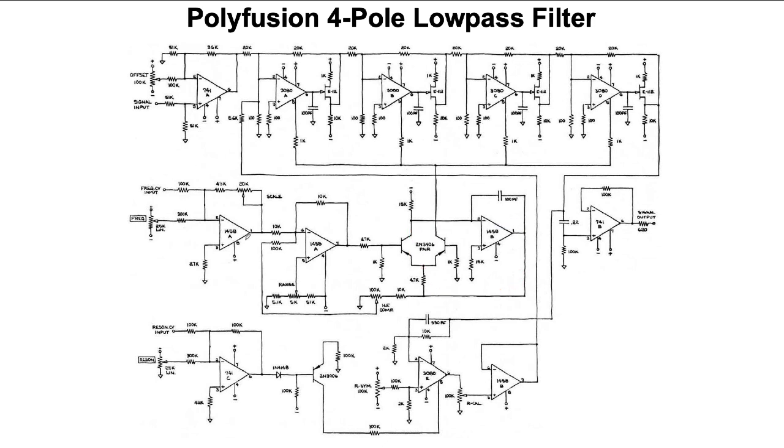And then we have some op-amps in front to combine different control voltages. So the versions of the circuit that we looked at that used NPN transistors needed a negative voltage here at the base relative to the base over here. And that was convenient because we usually needed to mix several control voltages anyway. So having an inverting mixer stage at the front sort of dealt with both of those issues at once. We could mix signals in a clean fashion, and we could also provide that negative voltage.